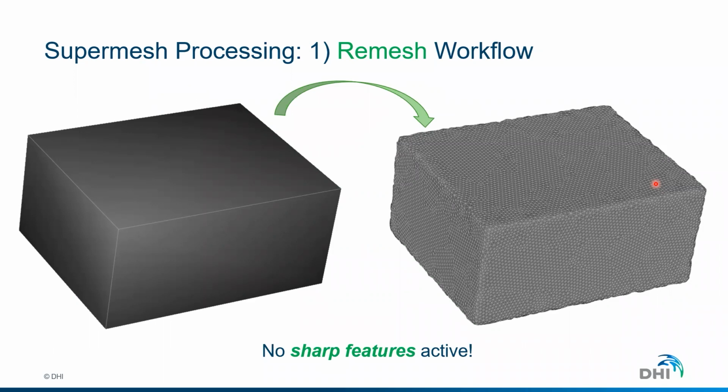So you can call this remesh operation. I put here a cube because it's the most obvious case where you will see the effect of this sharp features option. If you call remesh with the sharp features option, what it basically does is send this set of faces from the cube to the algorithm and maintain the edges, preserving the location of the edges.